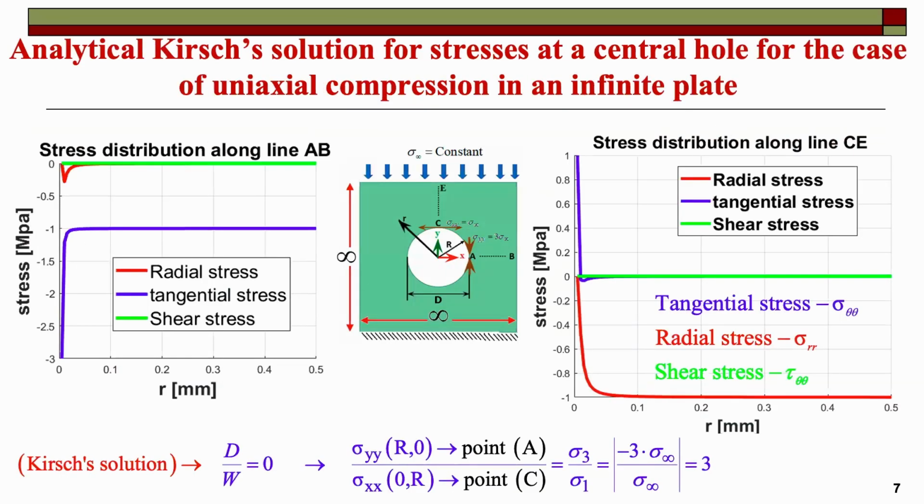This is the solution for the infinite plate, because at the surface of the hole there is no radial stress or shear stress. We have only tangential stress. So we get a stress concentration factor of 3 for the infinite plate. We know that.